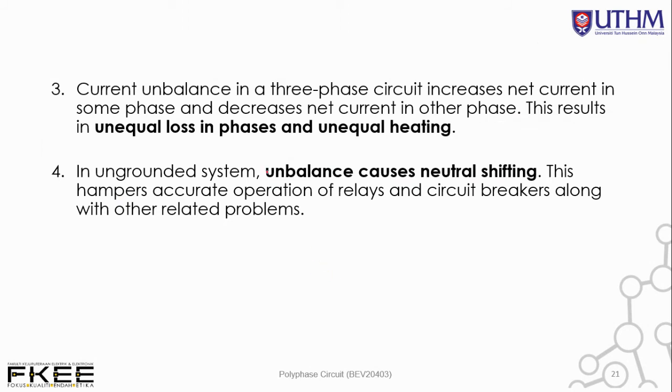So current unbalance in a three-phase circuit increases net current in some phases. On the other hand, it may decrease net current in other phases. This results in unequal loss in the phases and unequal heating.